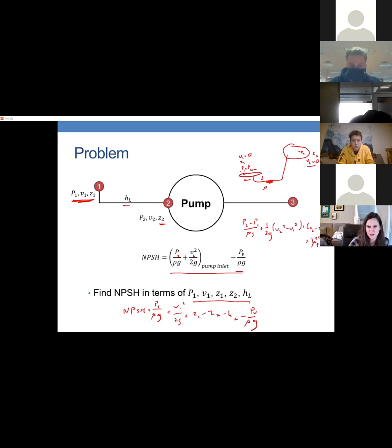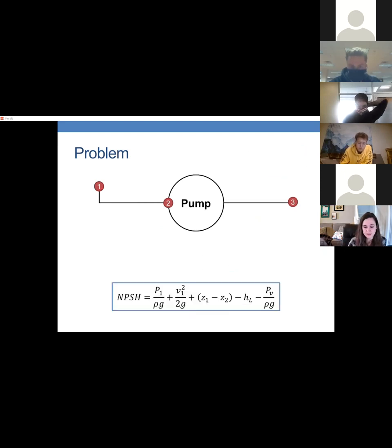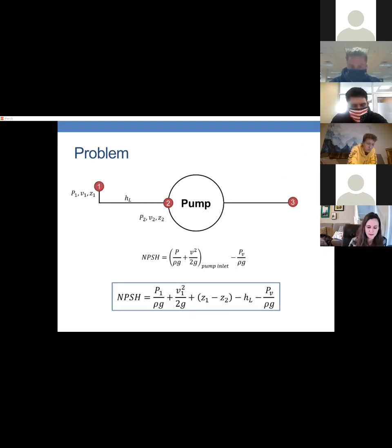Does that make sense? Mara, was it Mara who asked that? Yeah, it was me. I think I just need to write it down and go through it. Yeah, just go ahead and write it down and do the algebra yourself, and you should be able to see. Just write out this balance. Get P2 over rho g plus V2 squared over 2g on a side by itself, and you should see how it goes out. Okay. There we go. Looks like this.